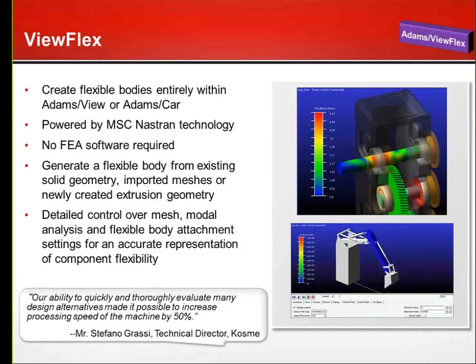ViewFlex is a relatively new tool that came out about 2 years ago, and this allows you to create flexible bodies completely within Adams View or Adams Car. So you don't need any external finite element program at all. What we do is we have a part of Nastran embedded inside of Adams. And it's very quick and easy if you just want to quickly create a flex body. It's a great way to do it.